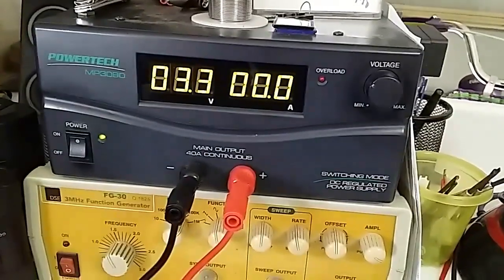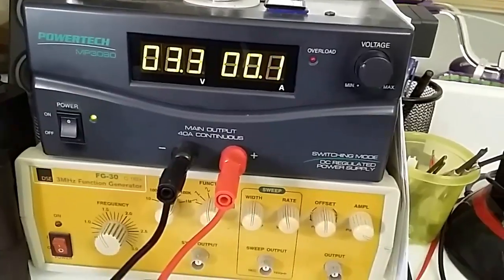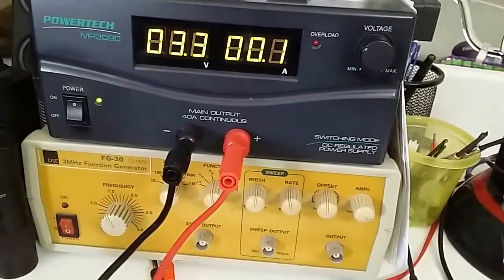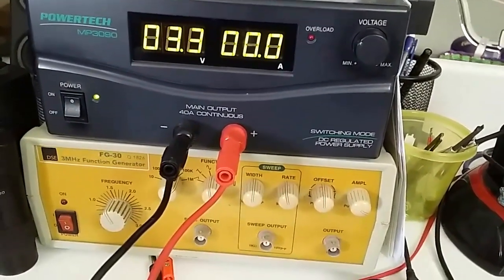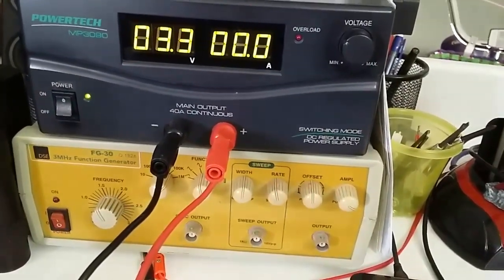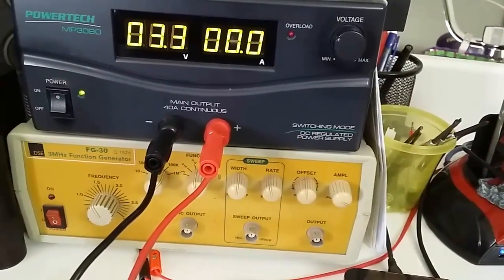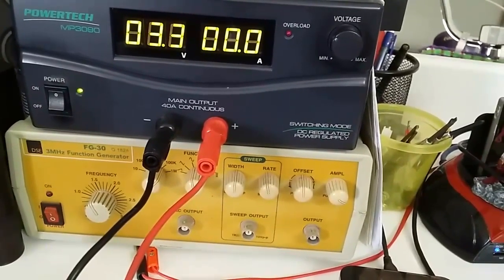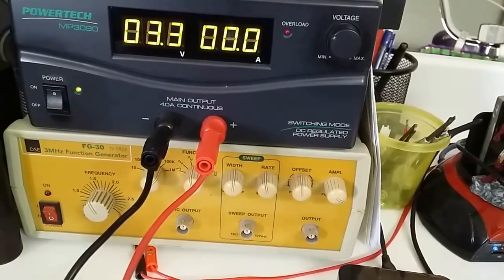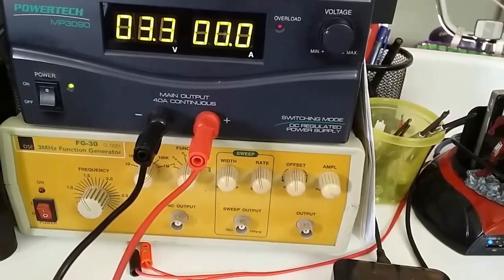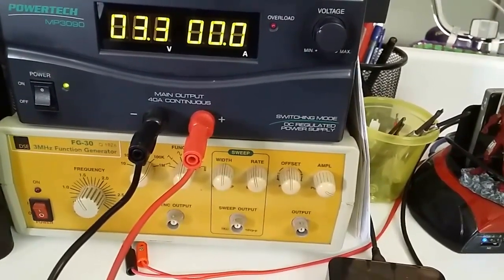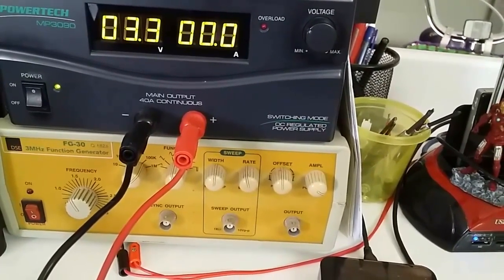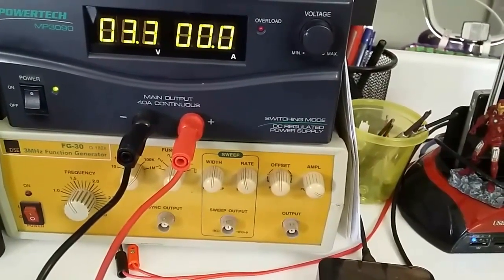Alright, so we're back again. What I want to very quickly do is some quick visual math, if you want to call it that, on the DUT, the device under test. So what we're looking at here is 3.3 volts on the input. That's what's coming out of our PSU. At the moment there's no measurable current. I'm sure there is current there, but there's no measurable current on that particular device. It's obviously down in the milliampere range.